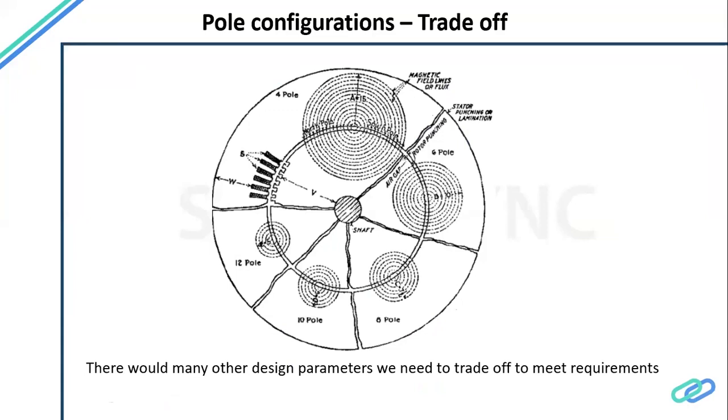So you will see Tesla is using some other technology, or BMW is using some other technology, but that is where the trade-off is coming from. So where you trade off, actually. This is another area: 6 pole, 8 pole. There are a lot of debates on 10 pole versus 6 pole versus 8 pole. And mostly you will see many times a machine will be either 6 pole, 8 pole, or a 10 pole,